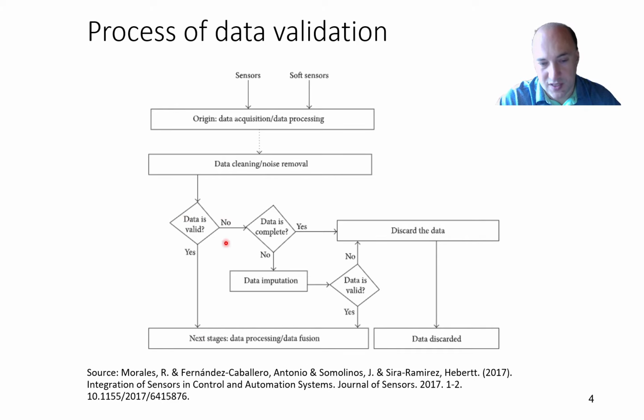Now if we find out that the data is not valid, we will first check if the data is complete. It means, for example, we might be missing some samples. For example, if you have digital communication, then typically the data is being transferred with individual bytes or packets. And when there is, for example, some interference that is quite short, it may destroy only one number or it may destroy only one packet. So then you have the previous data, the historical data, then you're missing one or few samples, and then you have data again, which is correct. And in this case, you may include the historical data by some average, for example. And if your data is not complete, you may edit it in there.